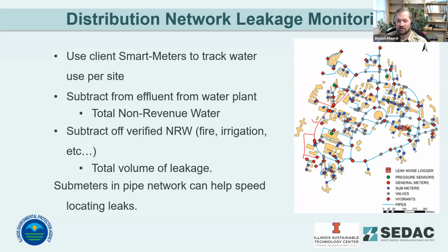So for both of these, it's false. When water demand drops, usually pressure is going to go up. You don't have water getting drawn out of the system, but your plant is recharging your water towers or repressurizing if you're using pumped pressure. So generally your pressure is going to go up when your demand goes down. And that's what exacerbates leaks. So that is a false statement. And then for pressure management systems, are most effective when you've got high topographic variation.